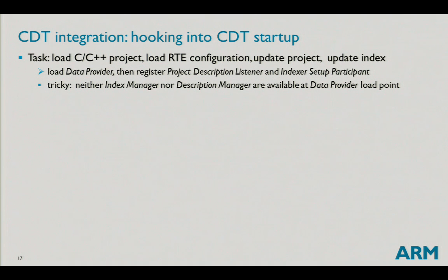But one situation is tricky, namely when we just start Eclipse and load a workspace for the first time. What we need is to load the C++ CDT project, then load the RTE configuration, update the project, and then let the index update work. It seems to be very simple.